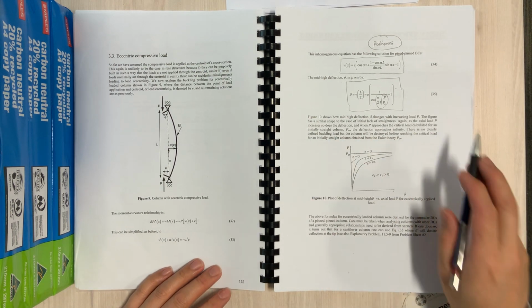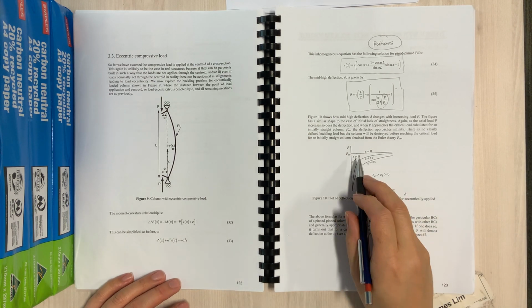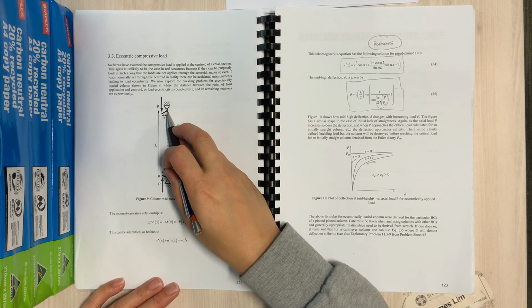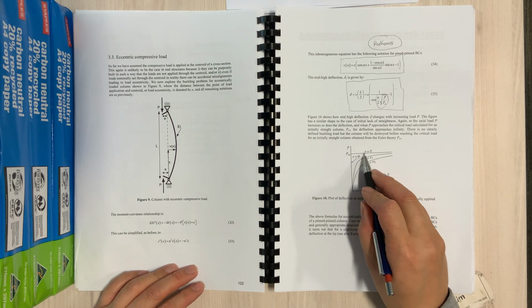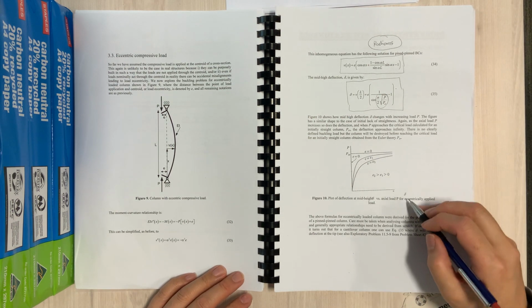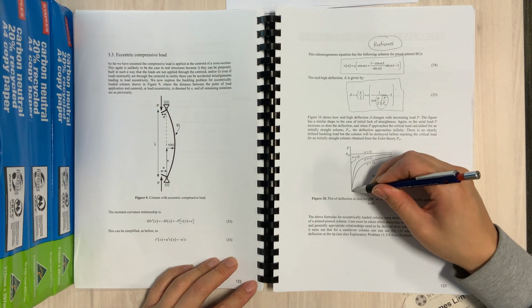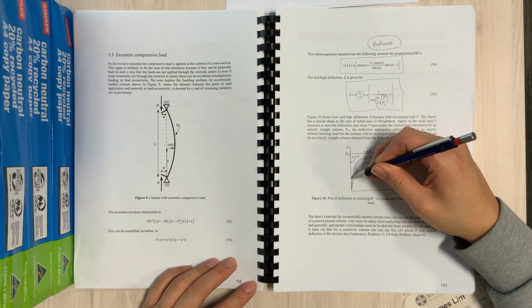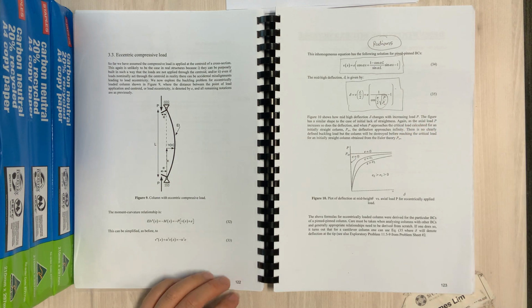So let's graph it. Figure 10 shows the graph. If the load is applied directly through the centroid, i.e. with an eccentricity of almost 0, we know that that's almost impossible. We would never be able to do such a test to that accuracy in the lab. The load path for your deflection at the bottom would just go up that vertical axis, and then suddenly at PCR the deflections would shoot off to infinity.